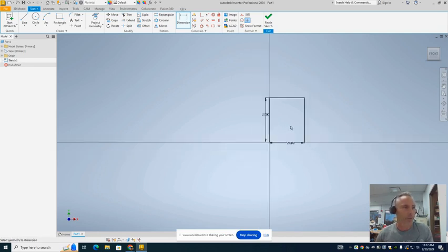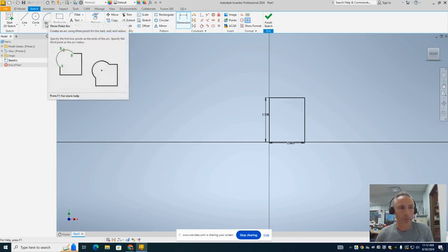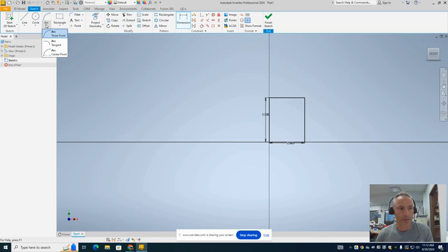All right. Now we're going to take an arc, and I prefer a 3-point arc. There's different types of arcs you can use, but the 3-point arc tends to work best for me. I'm going to start at that corner, come over to this corner, and pull it up just a little bit. If you pull it up too much, it's going to be really big, and we don't want that. We want it to be more of a flat arc.